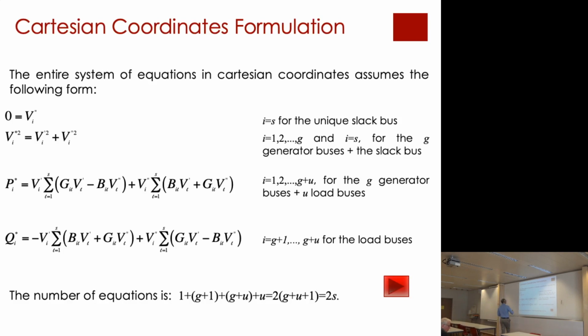It means that when you solve it, essentially by fixing Vi star, Pi star, Qi star, and you determine all the other free variables, you can get many solutions. You can also have an unsolvability problem. It means that if you fix some initial values, it can happen that your load flow problem does not have a solution. It means that your system cannot transport powers if you fix a given set of boundary conditions.